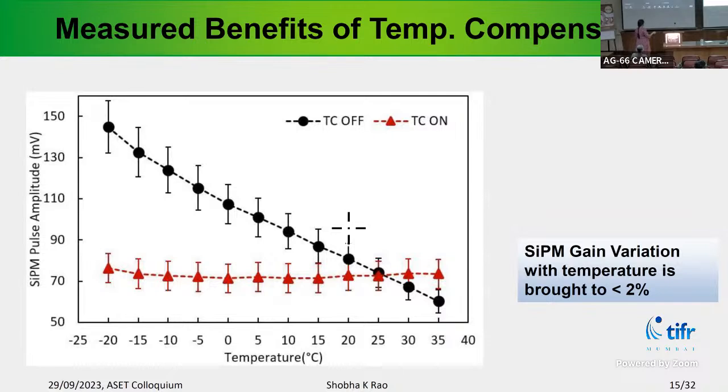So when you want an automatic compensation, that means your heating element temperature measurement has to be precise. And that, again, is what I'm trying to say, that you will not be able to compensate so well, and your variation is much larger over a small change of temperature. That will affect your output.